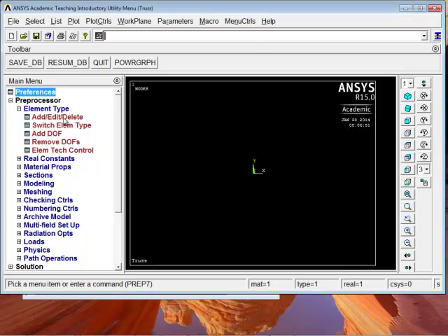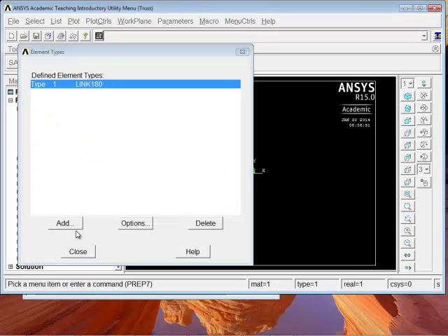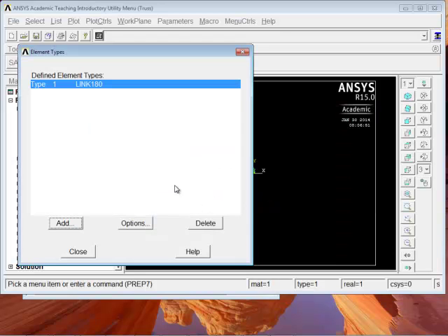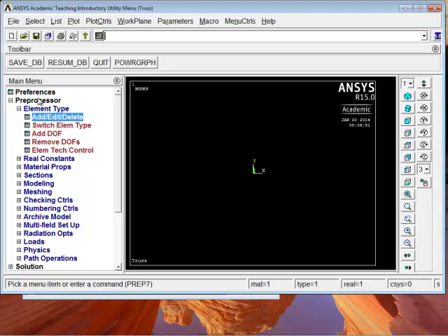Yes. And I'll go back in here and add elements. So now I got structural, thermal, magnetic vector, magnetic, electrostatic circuit. So you can see how it narrows it down pretty quickly to stuff you're probably going to be useful to. All right. So I'll leave that open so you can see everything in case you forget to check in the future, but that's helpful along the way. All right, so we added our element, link 180.